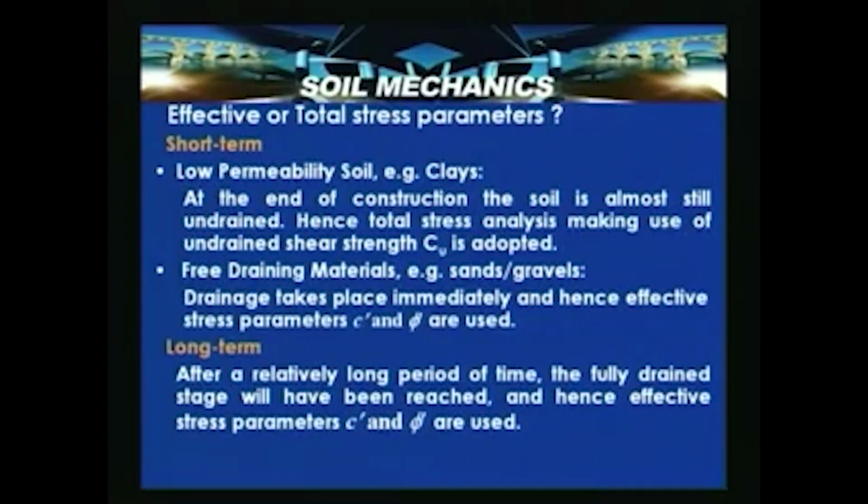Now, having discussed this, if you remember, there are two stress parameters which come into the picture. One is the short term stress parameter, the other is the long term stress parameter. In soil mechanics, for long term conditions they are effective stress parameters, and for short term conditions they are total stress parameters. When to adopt these depends upon the short term and long term stability conditions.